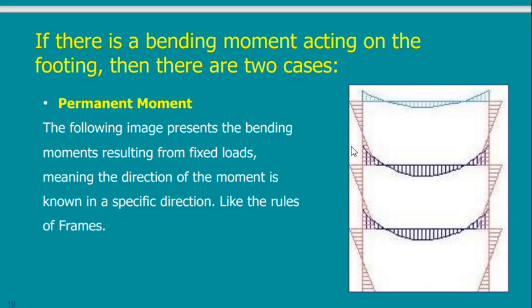If you move to the right or move to the left, then in this case you will add moment, because your weight will be multiplied by the distance between your CG and the CG of the raft or the plate where you are standing, and you will cause an additional moment. So why not, if I have moment here, I take this moment, divide it by the normal force I have from the column.